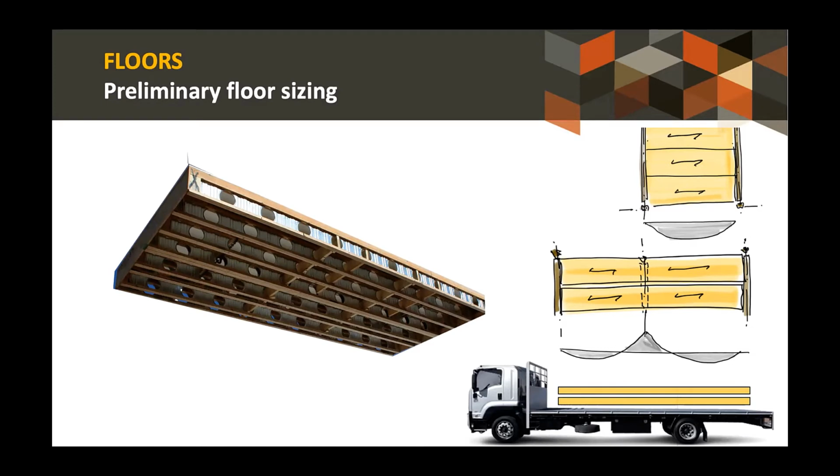Something on floors with respect to acoustics is that some very enthusiastic acoustic engineers may try and request that floor diaphragms and floor structure break across the boundaries between adjacent units in order to get the sufficient acoustic performance. We would strongly encourage floor structures and diaphragms to be continuous as far as possible and to look for alternative solutions for upgrading the walls to achieve the acoustic performance.